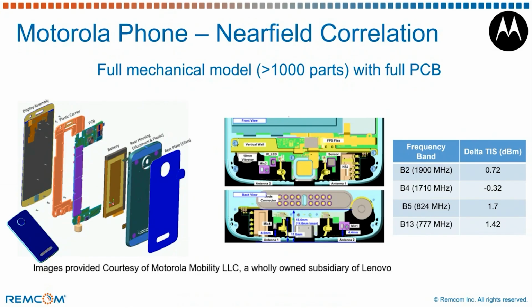And we would like to present this data from Motorola, as they were kind enough to let this be presented to the public, with the utilization of XFdtd for the design of antennas, the presence of the flex, and the antennas that the engineers have created with the matching, including very finely meshing these matching networks and the clips that connect and disconnect the antennas and ground the antennas.